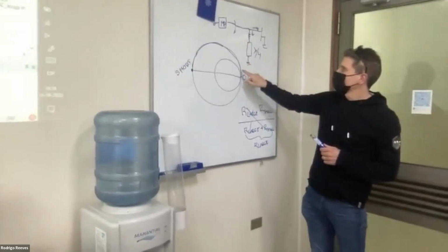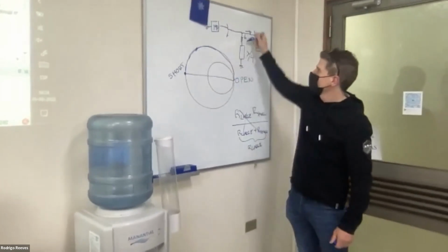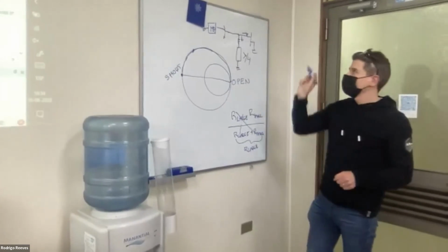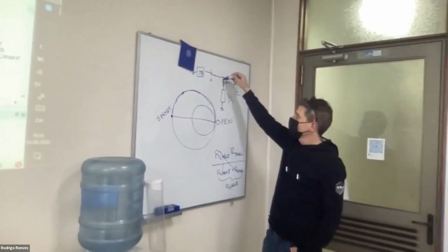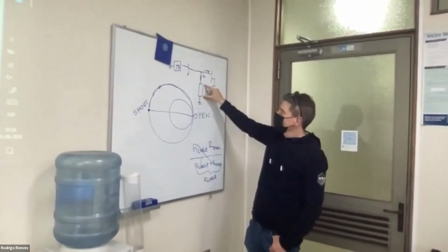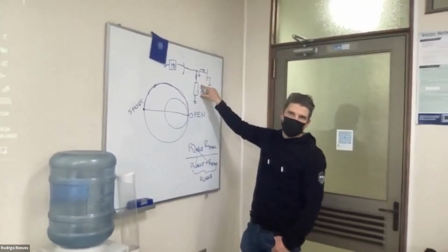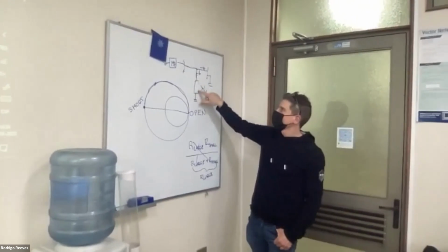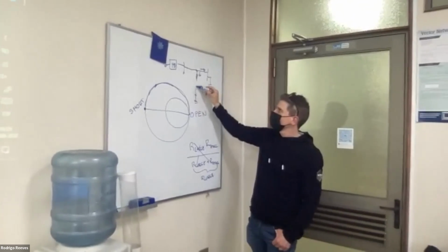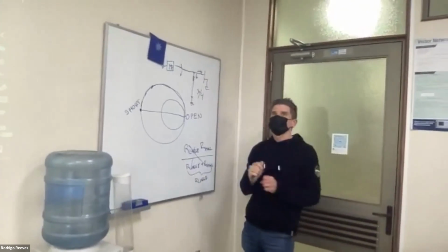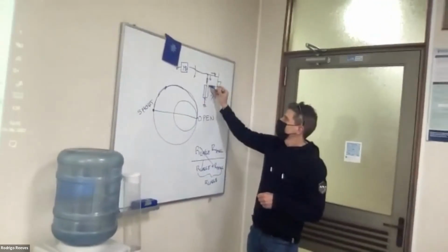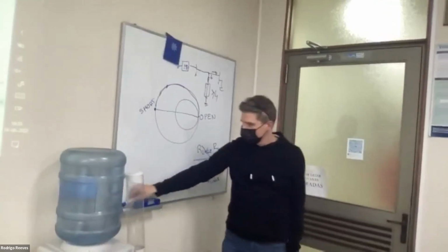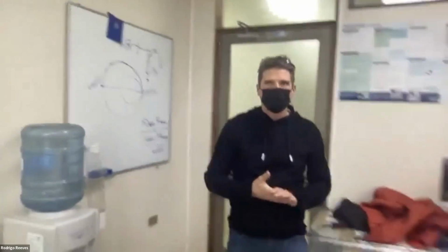But this has to be a bit long, because if you are not loading it here, then it would be zero. And now this is for the design frequency. So at any lower frequency, this becomes shorter and shorter, right? And at 1 megahertz, this is nothing. So you're actually loading it with a resistor at very low frequency. So it will stabilize your circuit a lot, no oscillation. So that's one other thing that you can use. Actually, I needed to use it because I couldn't get rid of that peak.